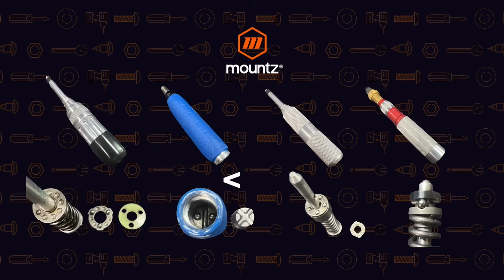In our next example, we have this particular driver where it has the spring mechanism inside the housing, and then we have stationary ball bearings inside of here, and then as the drive turns, these ball bearings will then allow this mechanism to move, and it will then compress the ball bearings and the spring, and then release after it goes up and over the particular segments here on the drive mechanism.